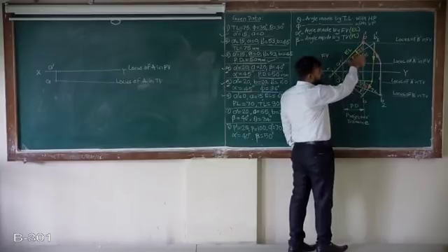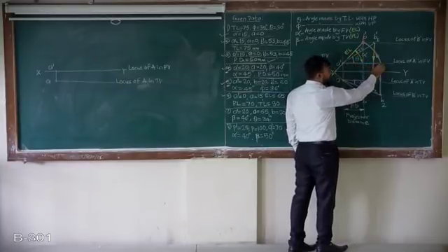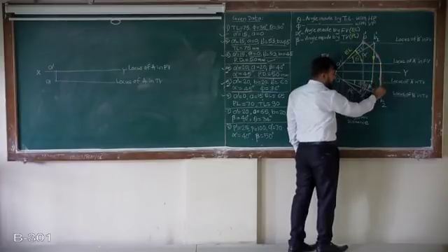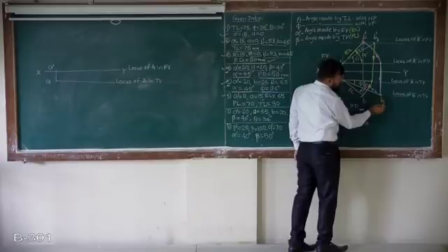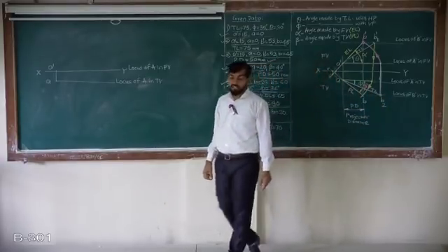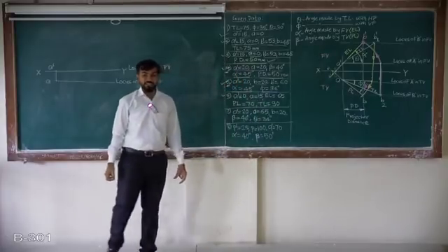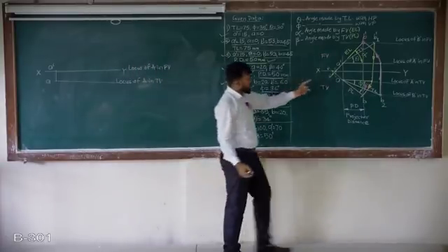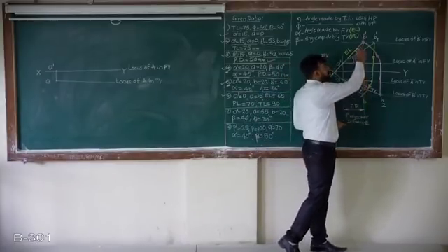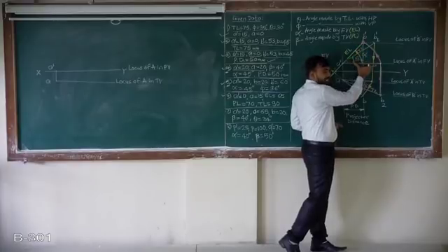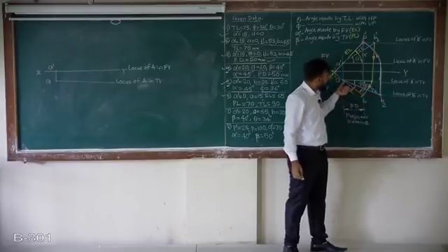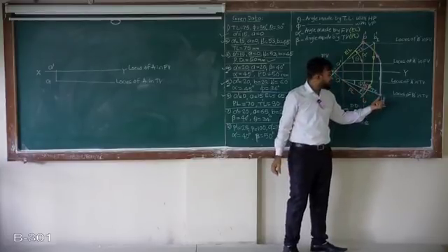That means when this EL is parallel to XY, if I extend this EL line into the top view, we will get point B2 when we know the true length or true angle phi. So if you know the true length or angle phi in top view, you can easily get point B2. How? Just make EL parallel to XY and project the EL line. On that line, you mark the true length or phi, and you will get point B2.